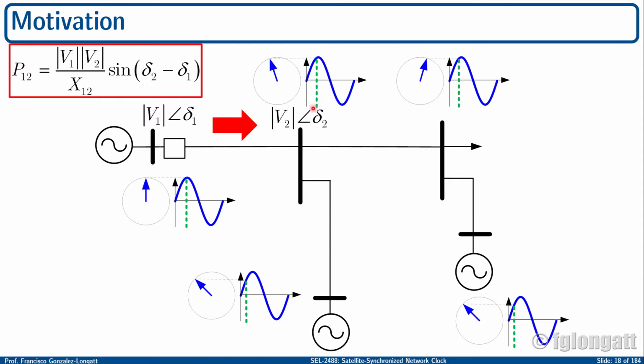For instance, here in this bus bar, I have on the left-hand side the phasor representation, and on the right-hand side, the time domain representation. The time domain representation is beautiful. You can see in blue color the beautiful sine wave. But one of the issues when you are using sine waves is the mathematical problem of handling sines or cosines. Many years ago, we started to use phasors. Phasors are extremely helpful for mathematics when you are running power system analysis.